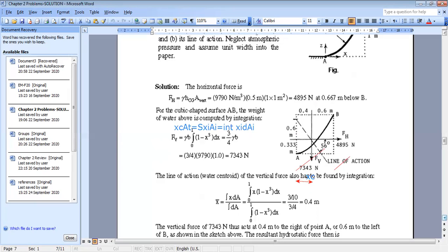In the other problem, you had large surfaces. So I have a square and I subtract from it a quarter of circle. There are two big parts. Then you do sum xiai, or you do sum of moment because it's equivalent. Because I told you the force is proportional to the area. So in the previous problem, when you multiplied A by gamma and width, you get a moment. So understand the concept, and for each problem, use the corresponding concept.